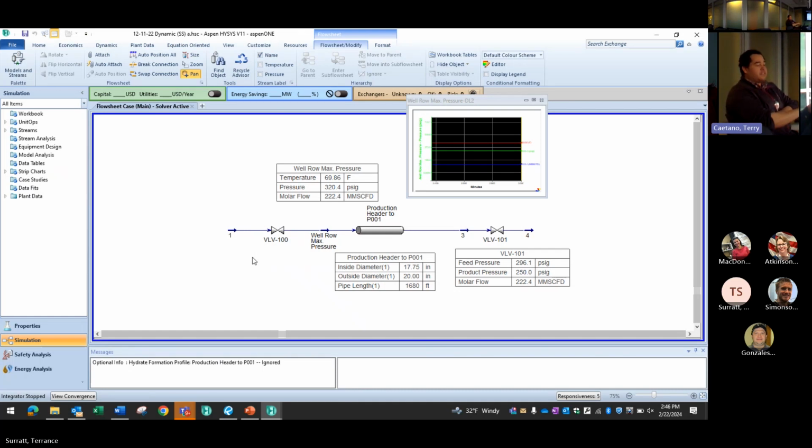But in this case, I wanted to distill it down to the simplest question I could ask. And if I could prove that in this case, the valve will close in time to prevent overpressure, then in all those other cases with less conservative assumptions, I can say that this valve would be adequately sized. The closure time for this valve would be adequate. And so what we have here is basically the header, however many feet it is, and our total flow rate headed into the drill site for production.